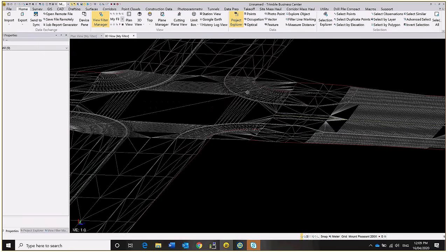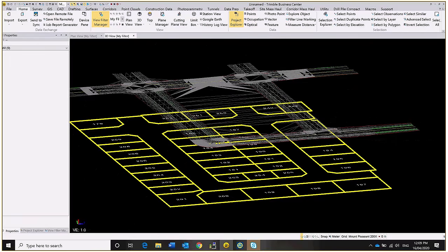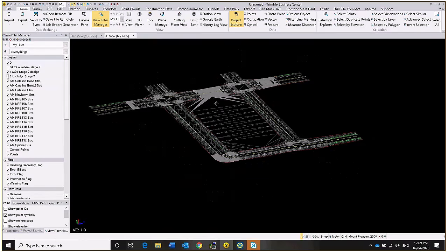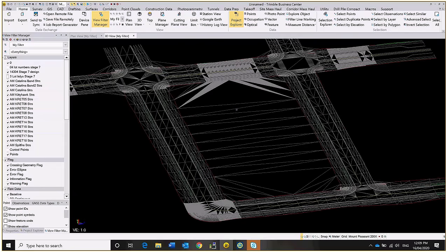happening. We can also see here that the property information is on height 0, so just for this purpose I'm going to turn that off. Alright, so now we have just our surface in here. Well, not our surface, it's more triangles at the moment, so if we click on one, it just comes up as a 3D face. If you hold down Control and Shift, you can exaggerate your surface as well, so you can have a look at it a little bit better and see what's going on.